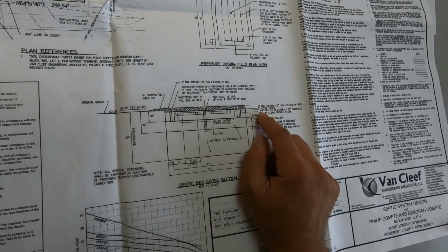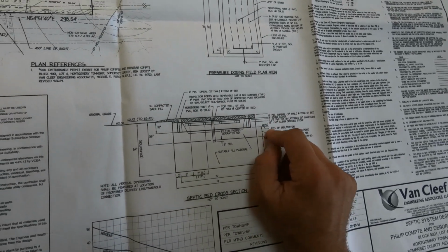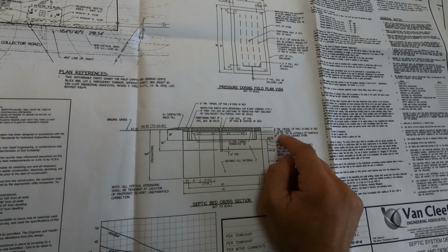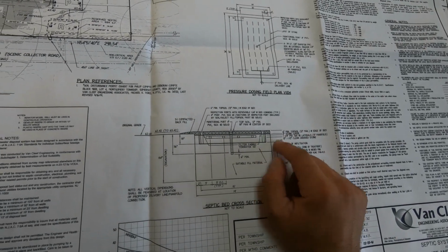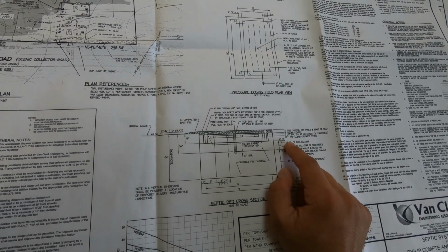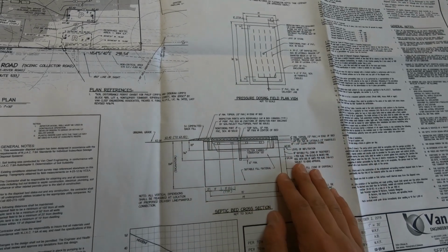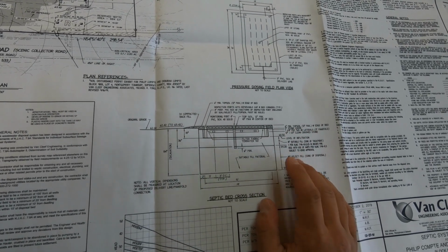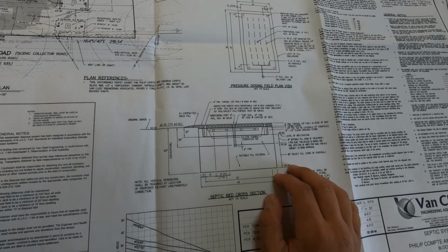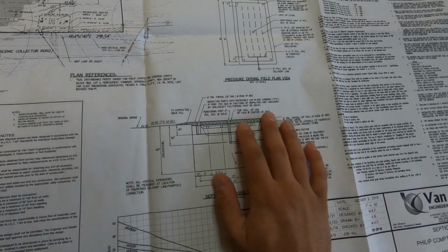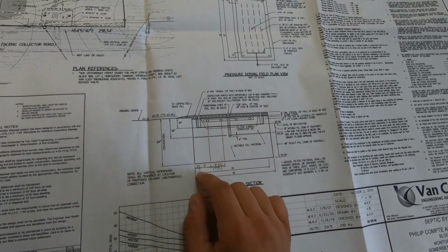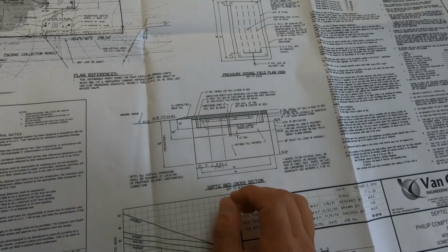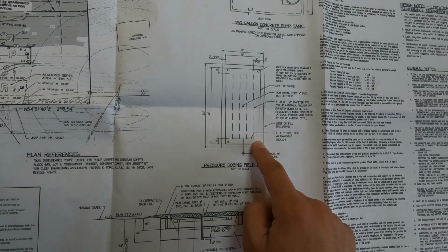And then for this job, since it's pressure dosing, we're using 1.25 inch PVC laterals with a 3-inch manifold. Again, on pressure jobs, it's usually 1.25 inch PVC. On gravity systems, there's usually a distribution box, and then the pipes are usually, I think, 3 inches is one of the common ones. But anyway, that's what you check after that. You just want to make sure that it's at the right height. They're using the right thickness of stone. They're using the right kind of stone, and that the pipe layout is similar to what's shown on the plan.